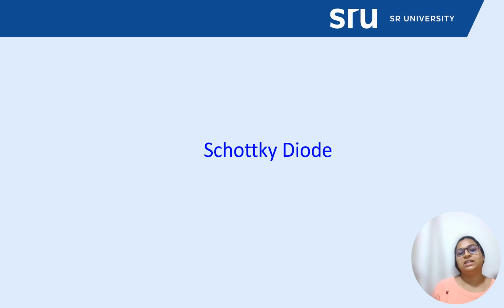So what is a Schottky diode? It is also a semiconductor diode, but it is more special than those we have discussed earlier. It is basically a metal-semiconductor junction diode that has a very low forward drop compared to the normal PN junction diode, and can be used in very high speed switching applications.